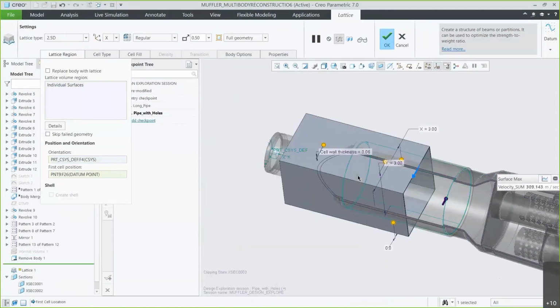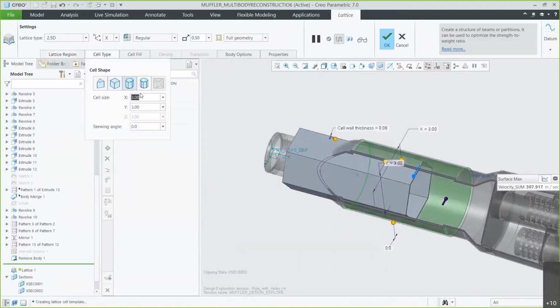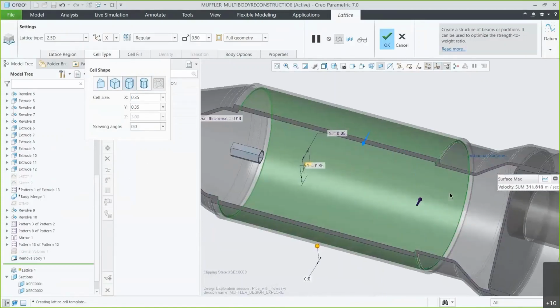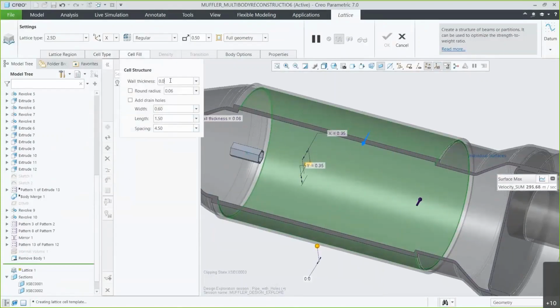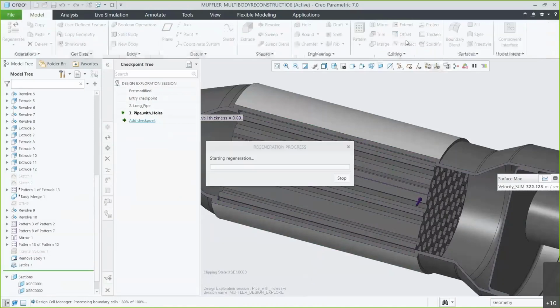We can do lots of different 3D shapes, or like what we're doing here, more of a 2.5D shape. Change it to a hexagon, change it to a square. And this one's a bit big, so we'll size it down. Once we have that picked out, we can change some other parameters around it if we'd like to. This is starting to look a little bit thin, so let's change up that wall thickness, increase it by a bit. Here, let's visualize what that's going to look like. And if I like that view, we can simply accept those changes.